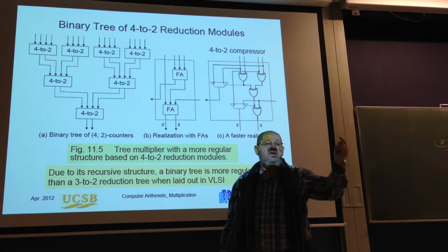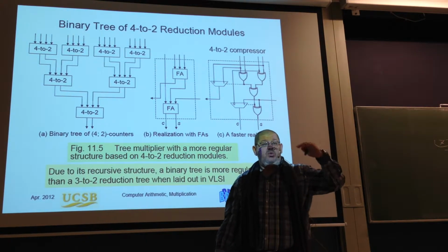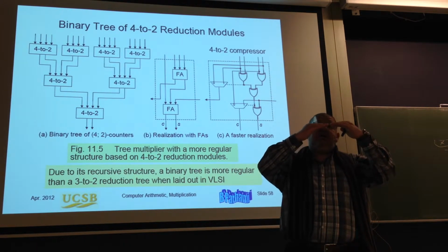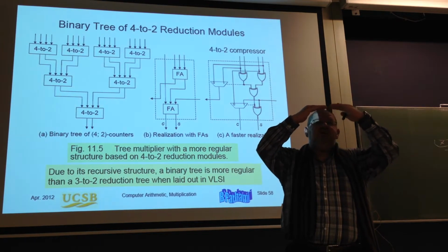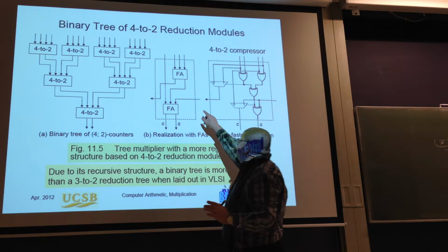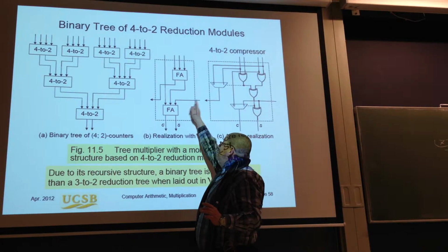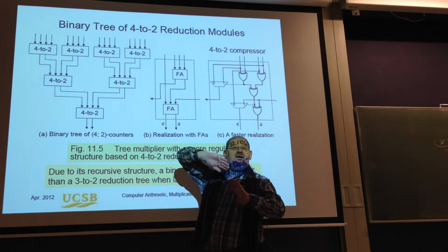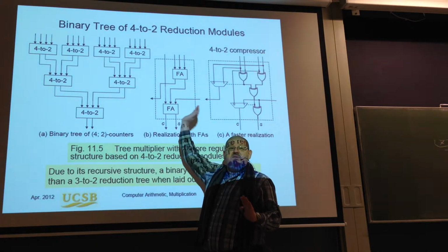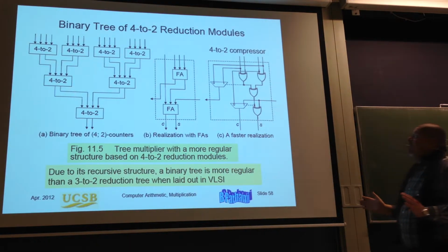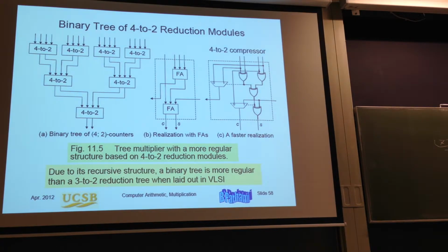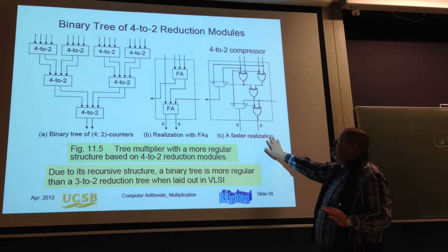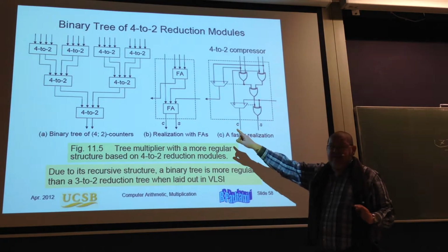But I'm also generating a carry in the middle of the calculation, which we discussed last time, that is not delaying the calculation because they are not getting one after the other. This is coming at the right moment. You see, this carry is coming from a previous position, but it's coming when I need it. If I would have routed this signal up, then they would be in data dependency. Here, there is no dependency. And now I see I can implement that with 2 full adders, cascaded in this way, generating what I need to, or I can implement it in this way. And this is faster than that.